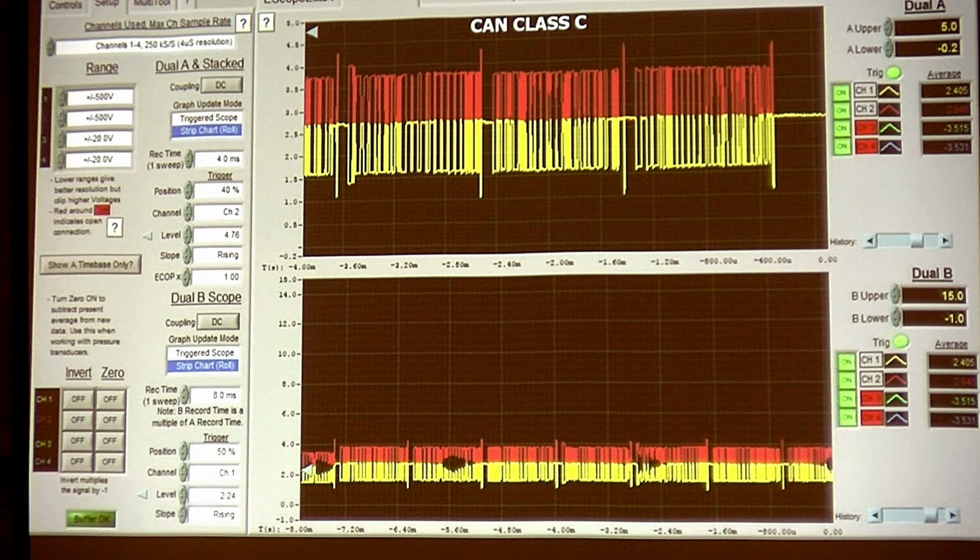This is a CAN signal, so this is CAN high speed. So basically, we can see that we have breaks here, and we can see these breaks in between here. That's my 3-bit idle period, right? In other words, the bus has to go idle before someone else can take control. When you see messages that are just lined up, boom, boom, boom, boom, they're all waiting to do messages. When you first turn the key on and you've got a scope on it, you watch it peg. All you see is solid transmissions of messages where everybody is trying to get on to do their message carrying. After a little bit, it will go and you'll have some idle time.